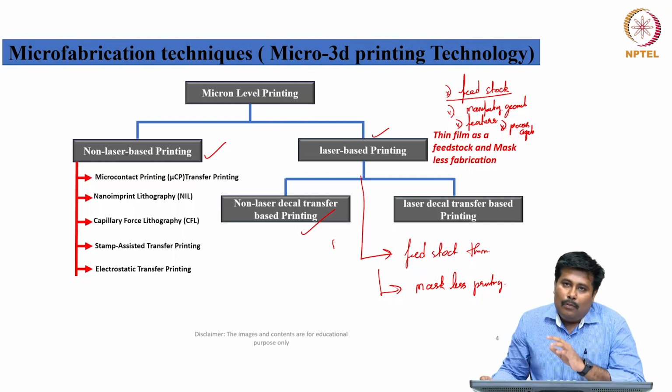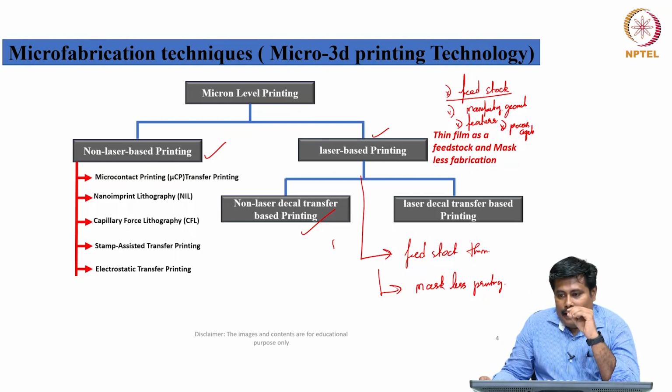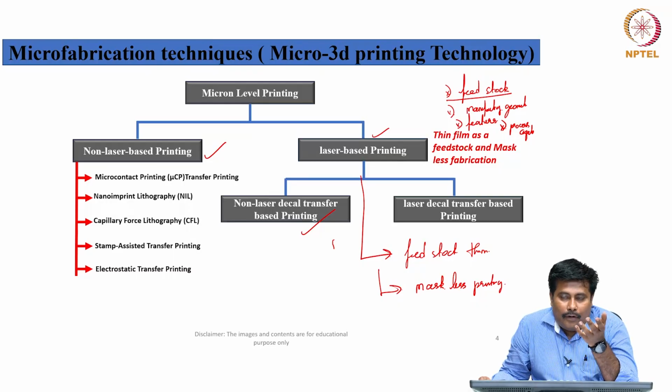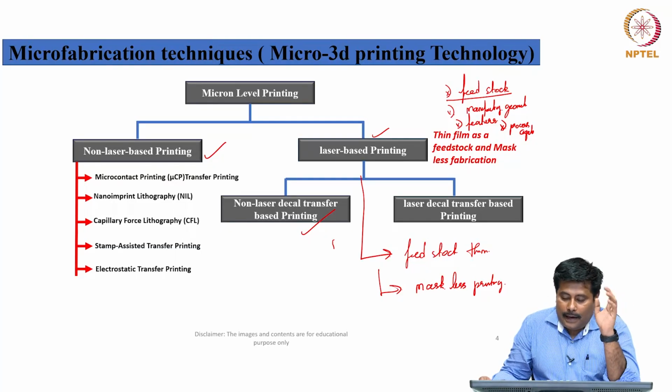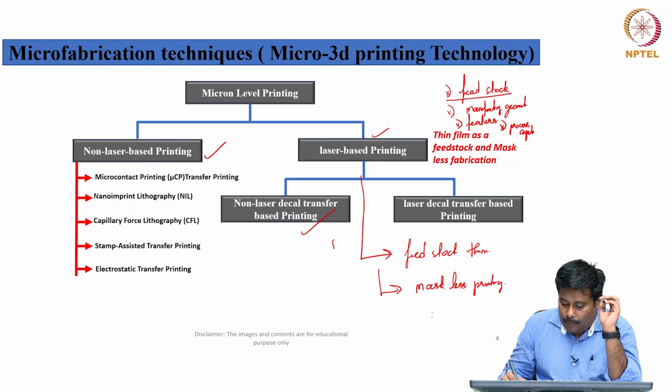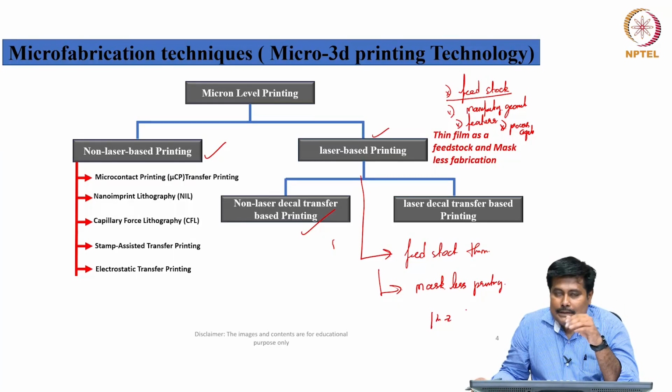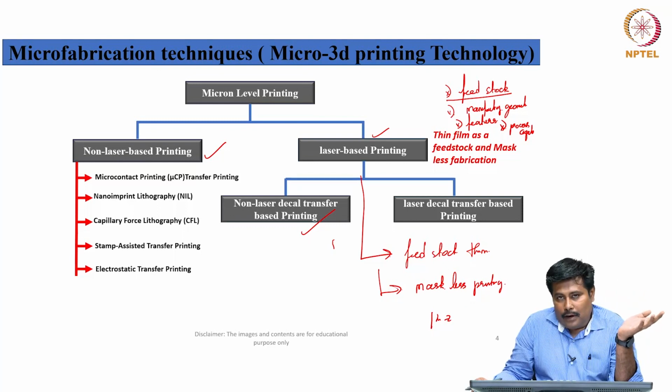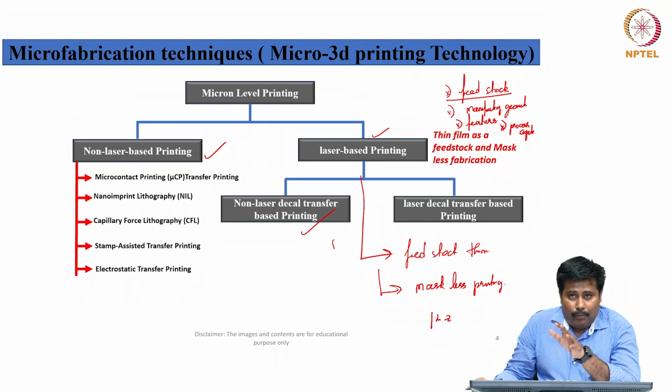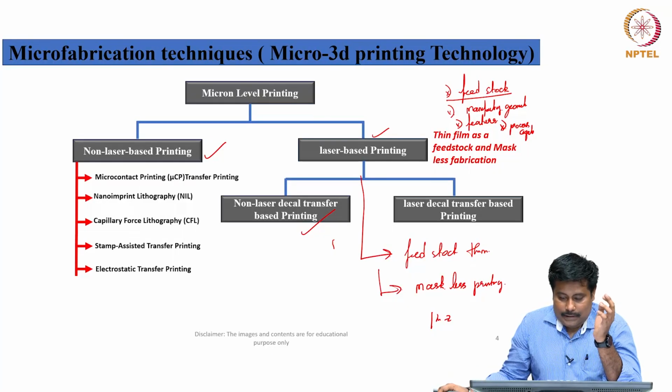The main motto of this maskless printing is that we do not need to align the mask. Normally, in most cases, manufacturing the mask itself costs a lot, and in certain cases even for 8 to 10 micrometer features we may need to manufacture a mask. So, this can be completely eradicated. This process has the capability that up to 1 to 2 microns we don't require a mask. Anything below 1 to 2 microns can go for a lithography process. However, between 1 to 2 microns, this has the capability to directly print the structures.